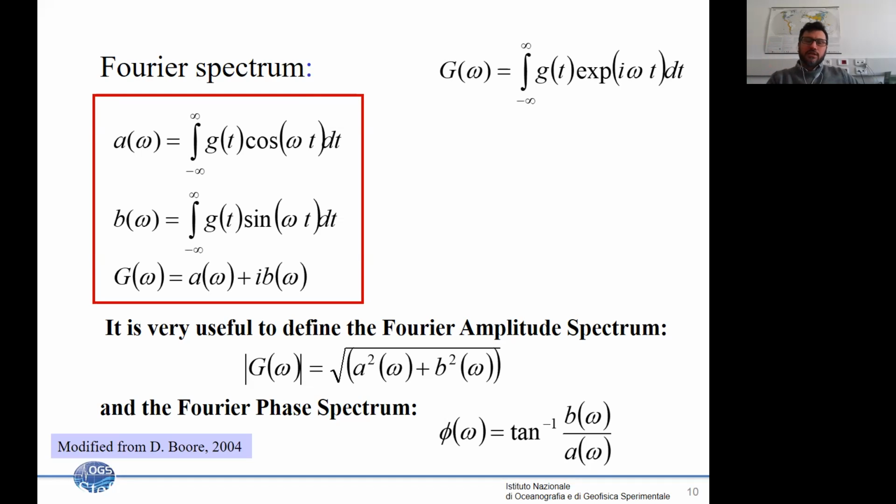And this will be information that we will use a lot in the following analysis, because most of the analyses that rely on surface waves are mainly trying to estimate the velocity at which the surface waves are propagating through the information on the Fourier phase spectrum. So try to keep this important point in mind.